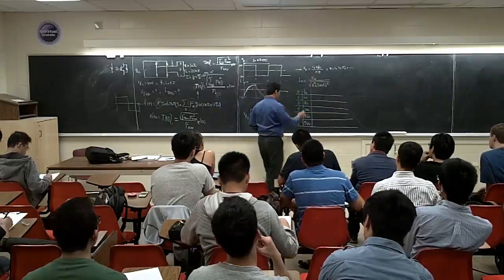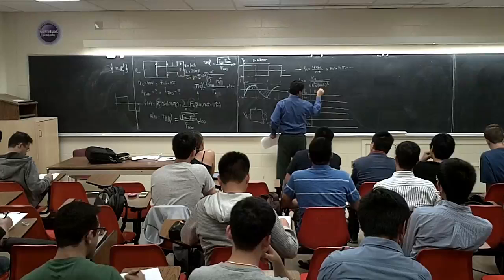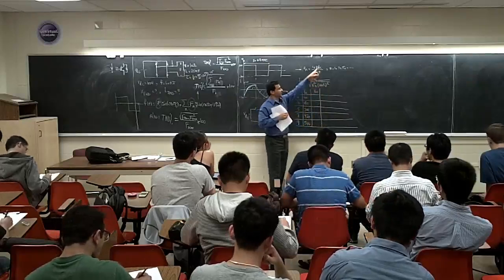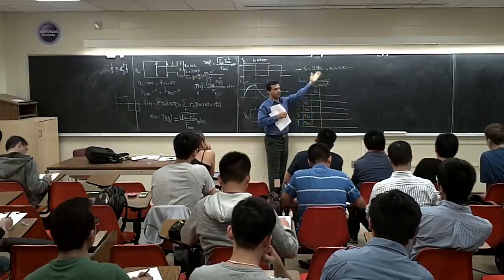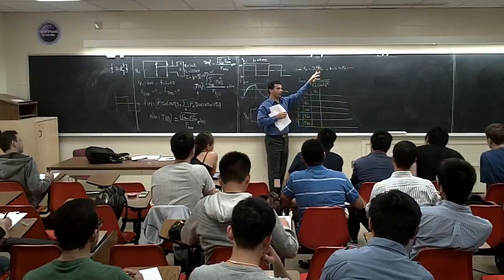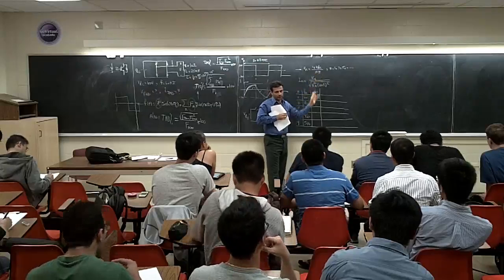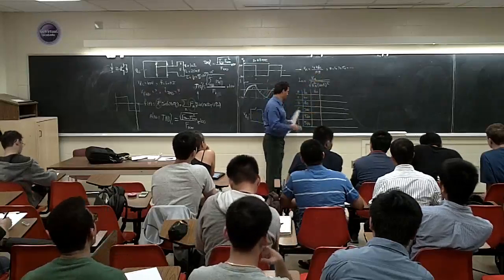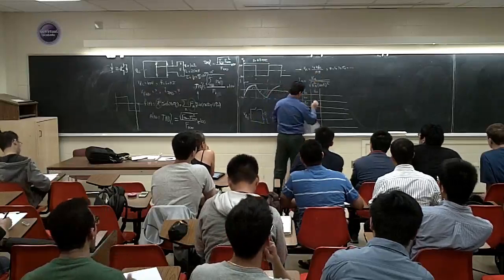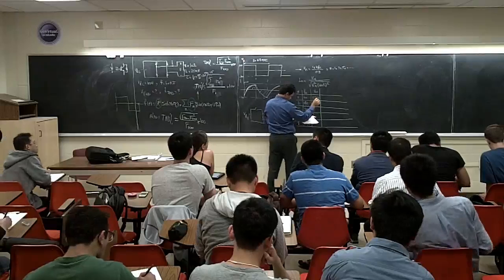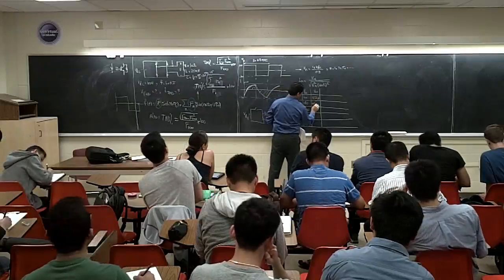Now, the next one is the Vn. How are we going to calculate Vn? VDC is 100 volt, pi is pi, 4 is 4, and now we are going to put 1, 3, 5, 7, 9 there, and calculate all of these, right? So if we calculate that one, V1 is going to be 127.3. V3 is going to be 42.4.